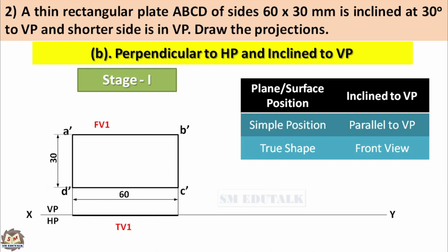Here, we keep the view on the XY line instead of placing it away from it. Now, let us see how to assign names to the top view. In 3D, you get the top view when you look at the plane ABCD from the top. In 2D, you get the top view when you look at the front view from here. You can see the rectangle's top corner points A and B. They are visible points, but the points directly under them, that is C and D, are invisible.